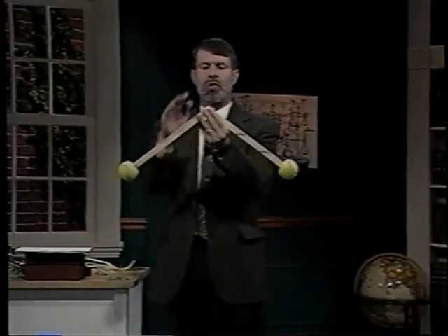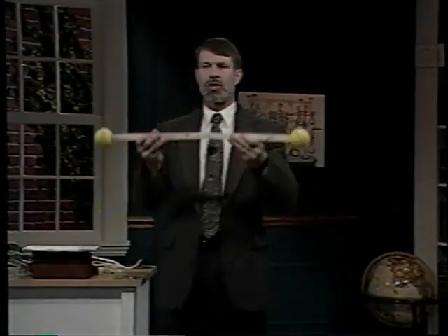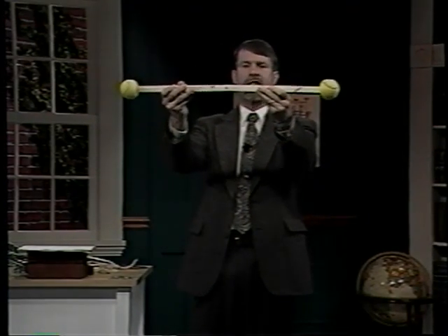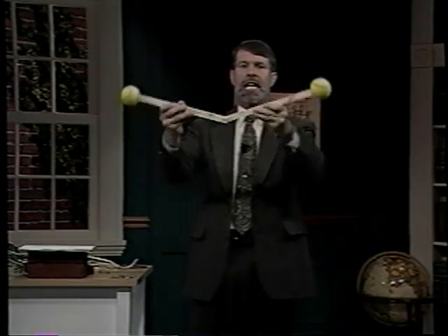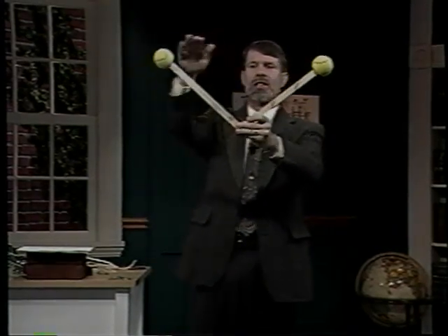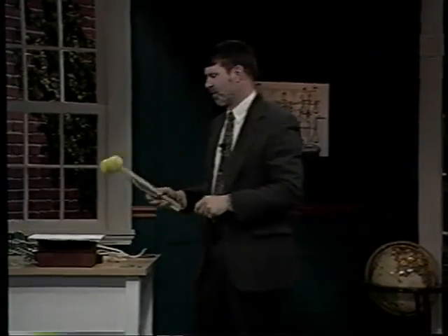But there are some very intriguing materials that behave differently. And these include materials that actually contract when they're heated. Now, how in the world could that happen? Think about this idea of contraction. You heat up a material, the atoms vibrate more vigorously, and yet the material gets smaller. It turns out these are materials that have very, very strong bonds between one atom and other atoms. And therefore, these bonds act like rigid sticks. At low temperature, there's very little vibration. And so the atoms are at their maximum separation. But as soon as you go to higher temperature, you get more and more vibration. The angles between the bonds get smaller. And therefore, the angle between the end members gets less as the material gets hotter. And this is what causes thermal contraction, a very interesting phenomenon of strong materials.